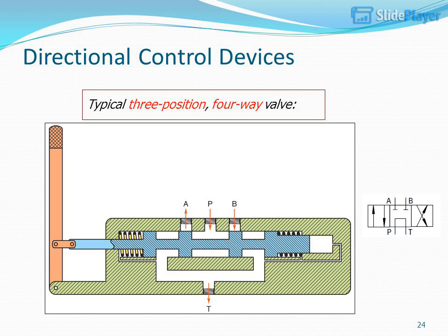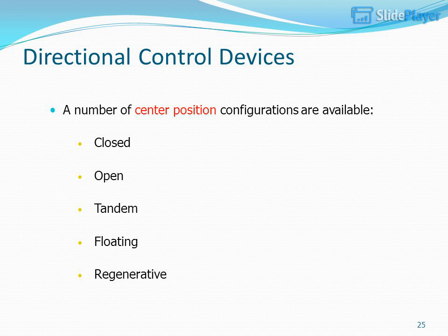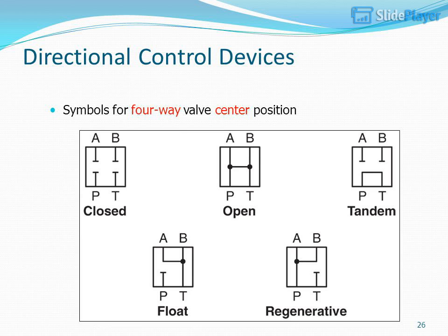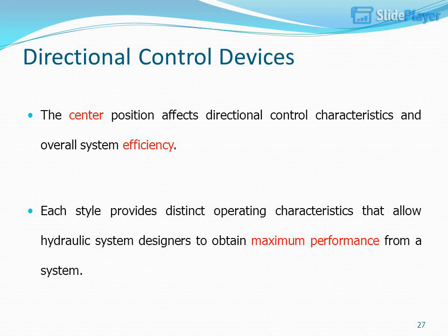Typical 3-position, 4-way valve. A number of center position configurations are available: closed, open, tandem, floating, regenerative. Symbols for 4-way valve center position. The center position affects directional control characteristics and overall system efficiency. Each style provides distinct operating characteristics that allow hydraulic system designers to obtain maximum performance from a system.